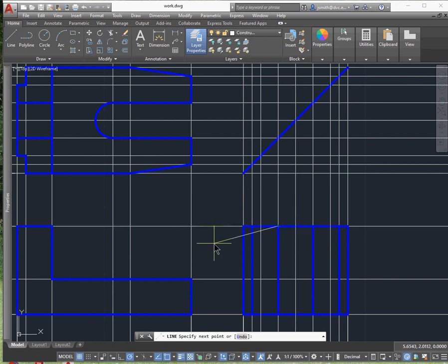So I'm just going to go ahead and build a horizontal line, and then type in rotate, and I'll select the point, which is at the top of the part, and the corner, and I'll just go ahead and type in 30 degrees. So when you type in minus, it goes actually clockwise. When you type in positive integer, it'll go counterclockwise. And so that's going to be my 30 degrees.